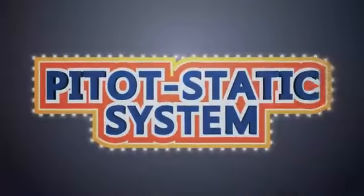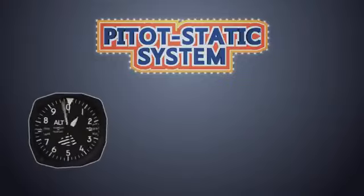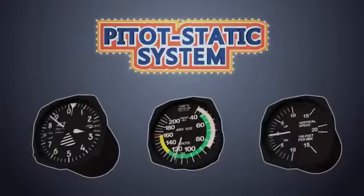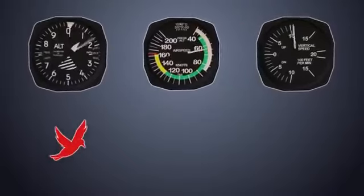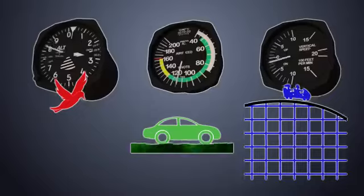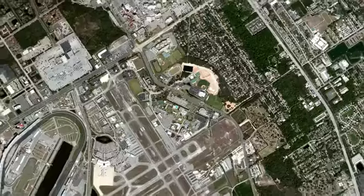The pitot-static system is connected to the airplane's altimeter, airspeed indicator, and the vertical speed indicator. These instruments tell the pilot how high they are, how fast they are going, and how fast they climb or descend. These are determined by measuring the pressure of the atmosphere.